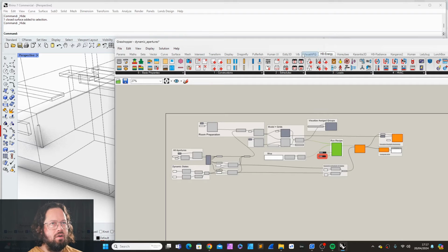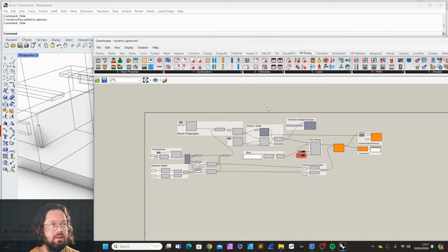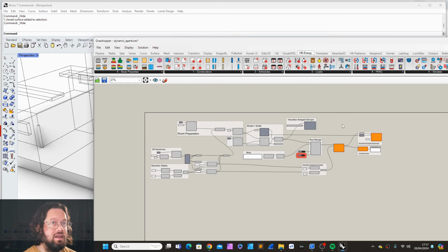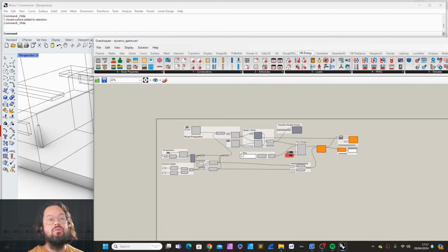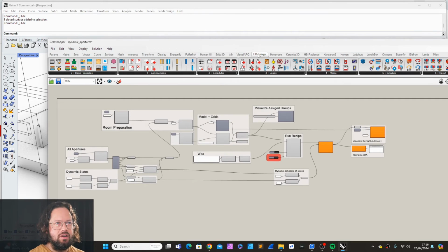Now this is a bit tricky, because if you want to have a dynamic object which changes its appearance over time, then Honeybee Energy deals with dynamic objects differently than Radiance. So it depends on what you really want to calculate. If you do energy calculations, then you can set a schedule for your shading device. And I did a video about that.